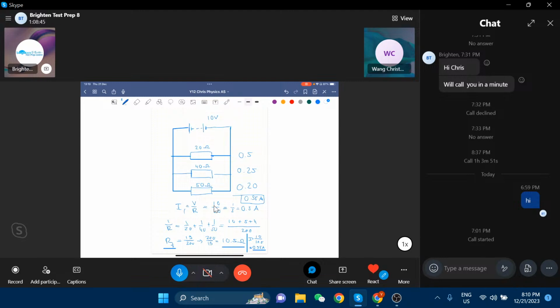Huh? So that would be another way to come up with the answer as well. Because we have calculated the first one, I can use the result and put it into the logical relationship that the ohm drives directly the amps, because the voltage is accordingly given. And henceforth I can just start to add up the respective currents. They are a direct consequence of the resistance, right? Because the voltage, as it's a parallel one, must be the same across each, like we said before. So I have to have 10 volts each because of that EMF. So that would be another way to do it.